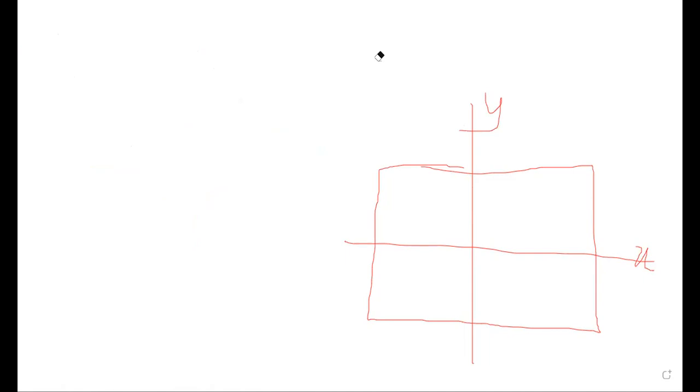Our building should move in the weak direction, right? So it should move in this direction, because Ixx is lower than Iyy, right? If you just take a beam like this, it is hard to move in this direction rather than this direction, right? So you know the reason. Ixx and Iyy, but why is it still moving in x direction first?